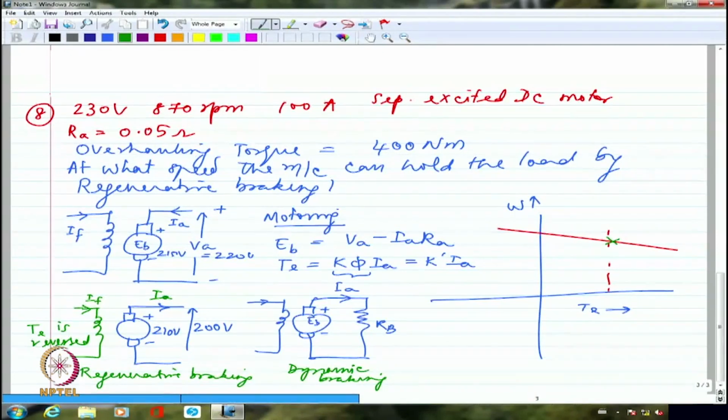So if the speed increases quite a bit, the speed might go beyond rated speed. If the vehicle is going downhill, or if it is like an elevator, 4 people have gotten in, it is coming down, there is hardly any control, it will just crash. That's what will happen if I don't have any control.